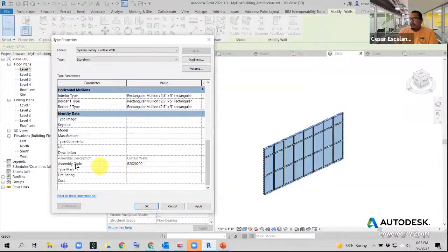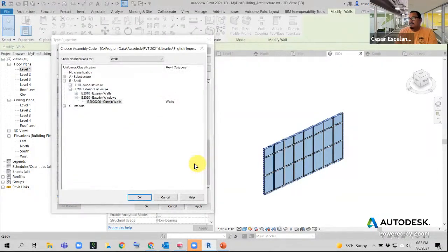All right, and then at the very end, notice that Revit also organizes the model elements using an assembly code. This is OmniClass. If you are familiar with classification systems, you are familiar with MasterFormat, UniFormat, and more recently the CSI, the Construction Specifications Institute, is also using UniFormat as a way to classify digital information and use it for pricing schedules.